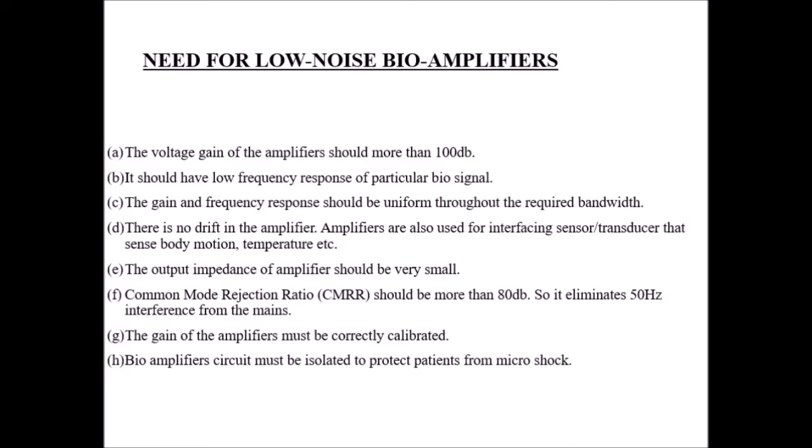Some of the features are there. The gain of the amplifier should not be more than 100 dB, and it should have the low frequency response of the particular biosignal. It should have the capability of identifying the biosignals, and it should differentiate the biosignals and noise.